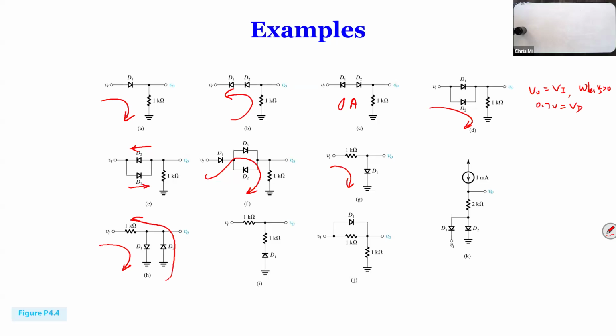And this one here, I. If you have positive, no current. But if you have negative, current can go this way. So this one says when it's positive, output is the same as input. When it's negative, the output is kind of half minus the D1 voltage drop.